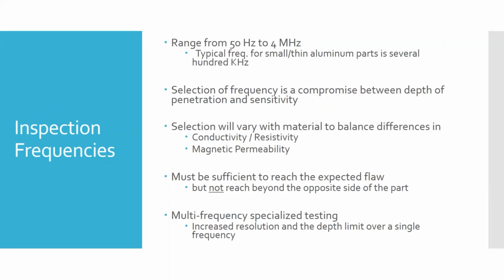But we have to know too, what kind of a flaw are we looking for? Usually when we're doing this, we're checking specific areas because we know a flaw is possible. We check around rivet holes because Aloha Airlines turned one of the airplanes into a convertible, and we know that cracking emanating from rivet holes is common. We have to check landing gear legs at the trunnion point, because every time the plane lands, the weight of the airplane is slamming on the trunnion. The trunnions are the big bolts that hold the landing gear in place, right?